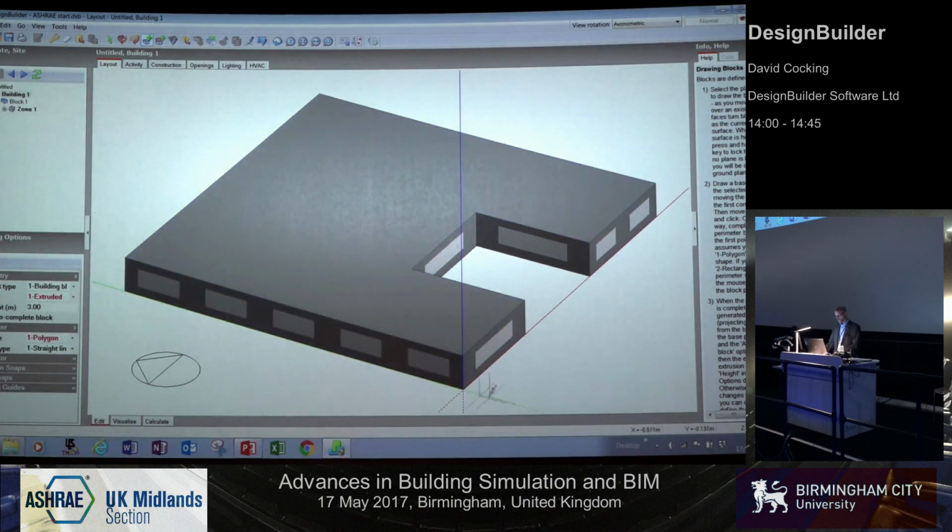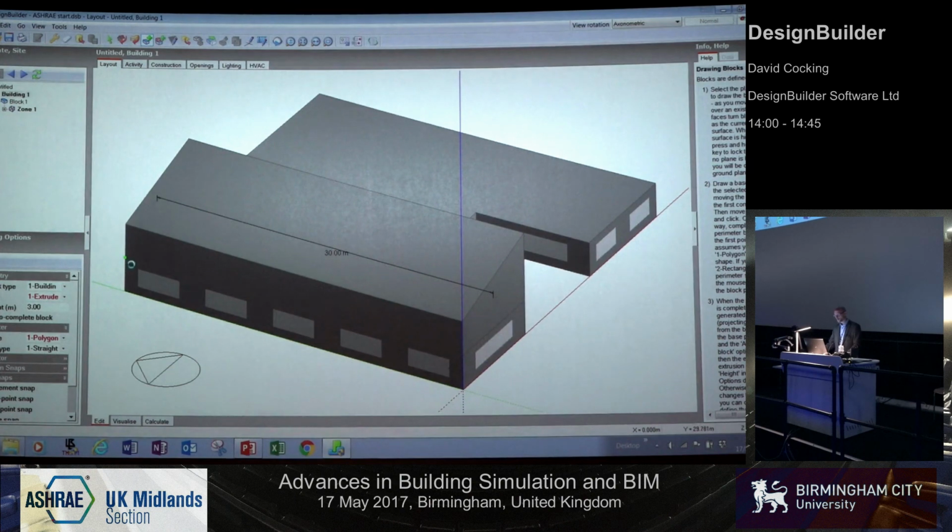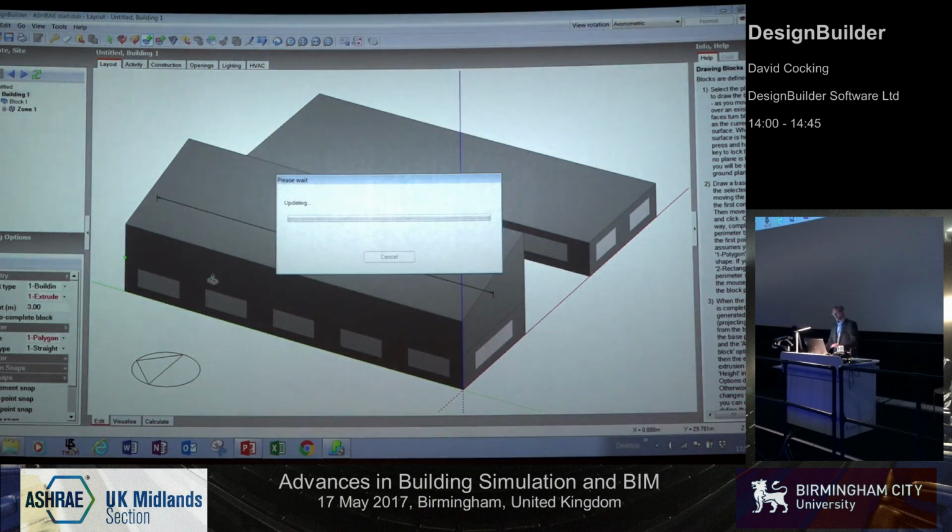So I'll just do that, and I'll choose an apex of, let's say, 6 metres up there, and I'll come back down, snap there to 3 metres and back this way, and pick up a snap point on that end facade, and that will line that end up with my existing one.